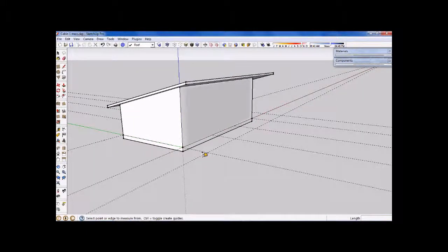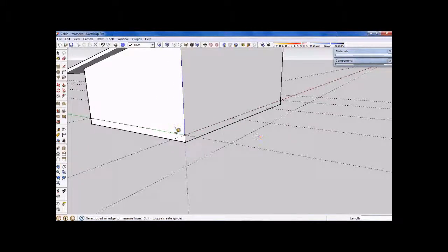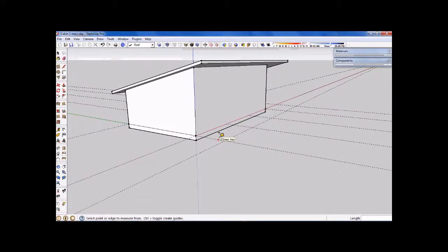Now, if I imagine the floor outside would be a 100mm thick slab sitting on a 50mm thick sand bed, if I was to place that directly on the ground, that would bring me up 150 above ground. Now, this building that we've set up at the moment, the floor level is 300 above ground. So if I come 150 below the floor level at the moment, that would set up the slab for the veranda area and the carport. In fact, maybe we'll first of all start constructing that slab first. So that might be a better place to start.